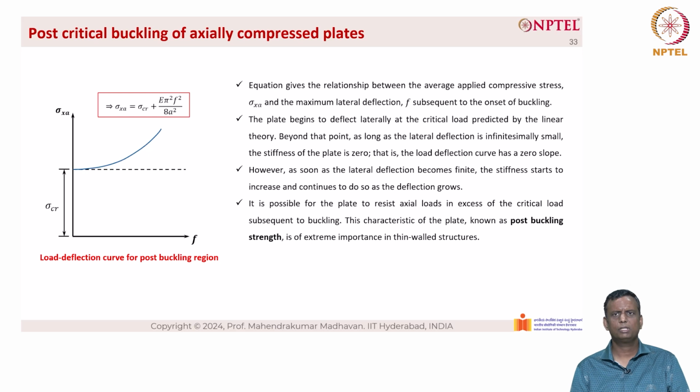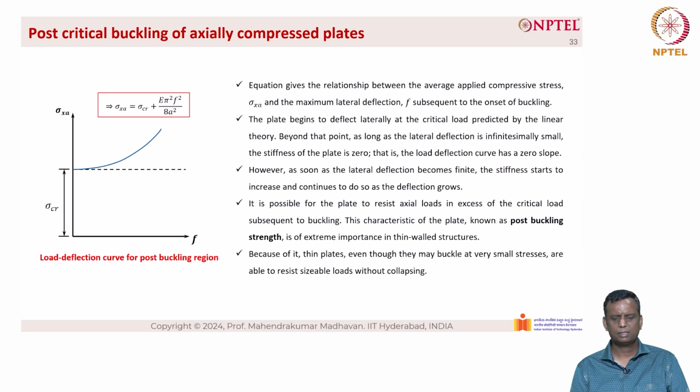It is possible for the plate to resist axial loads in excess of the critical load subsequent to buckling. This characteristic of the plate, known as post-buckling strength, is of extreme importance in thin wall structures. Because of it, thin plates, even though they may buckle at very small stresses, are able to resist sizable loads without collapsing.